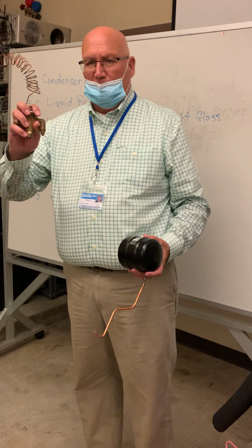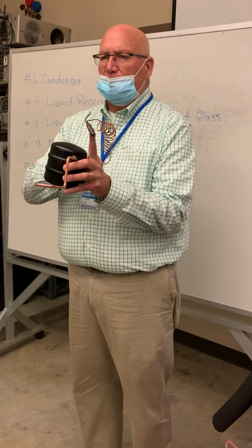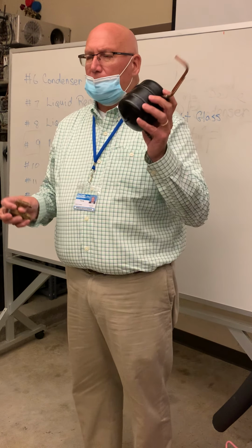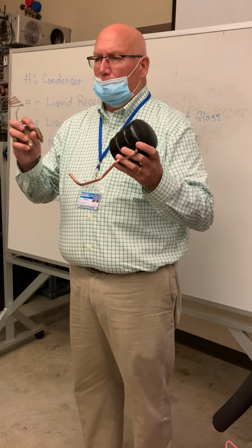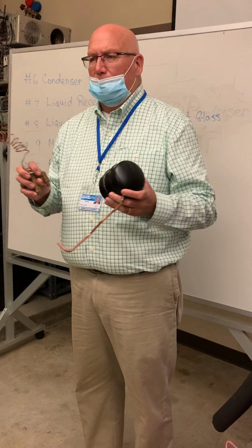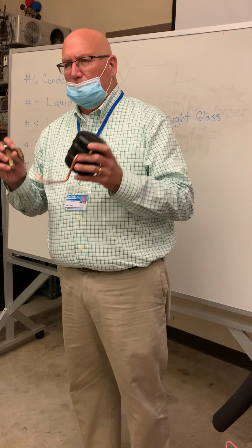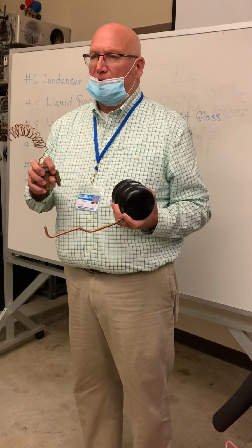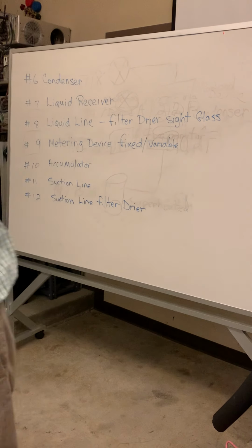The variable valve, the thermostatic expansion valve, is variable. It also measures the temperature of the refrigerant at this sensing bulb here. And it's going to say, I need more refrigerant from this receiver right here in order to maintain that amount of temperature and how it absorbs. So it monitors the system and calls on reserve when it needs to. Or when it doesn't need to, it chokes back the refrigerant and it rests in this receiver tank.